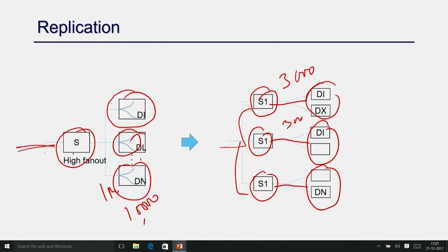So, what I just talked about, I just split this source into multiple sources now. And now I say there are 10,000 fan outs; how to club, which 3,000 I should put as the output of this, which 3,000 I put as the output of this, and which 3,000 I should put as the output of this source, right. Here I should always maintain the hierarchy of your design. It is very obvious that whenever there is a hierarchy in your design, all these nodes are connected a little bit, and the synthesis tool tries to place those nodes inside a particular hierarchy in close by places.